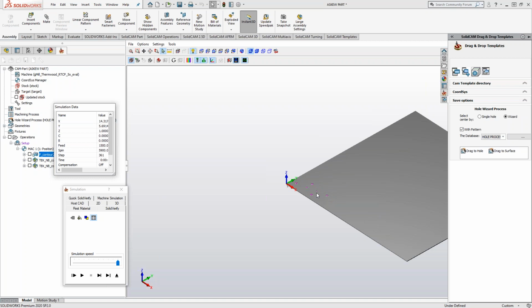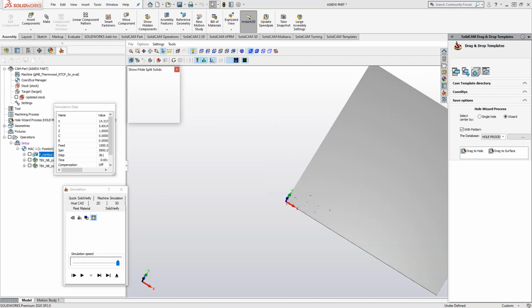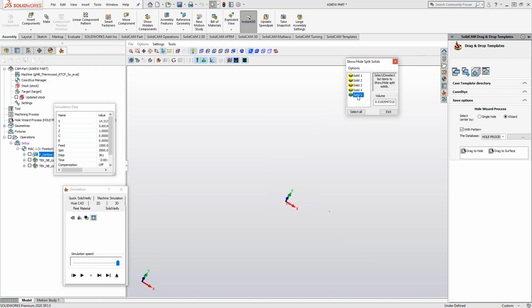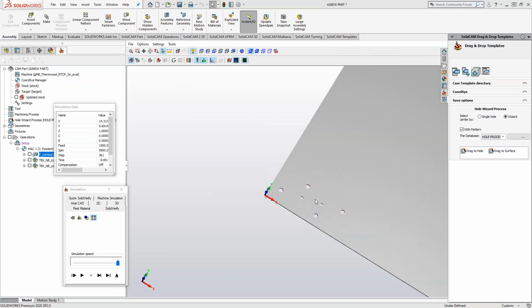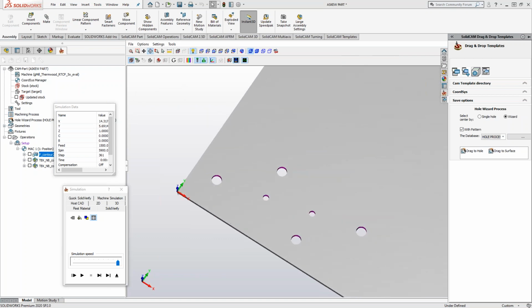If you have a part where you can do the Solid Verify, get a good view of it like this, maybe even remove the solids like we saw yesterday. So we got this one, this one, this one, pretty much everyone except for these ones. Just delete those, say yes, and then the remaining stock is what you want to carry with you. So this is what you can save into the future part.